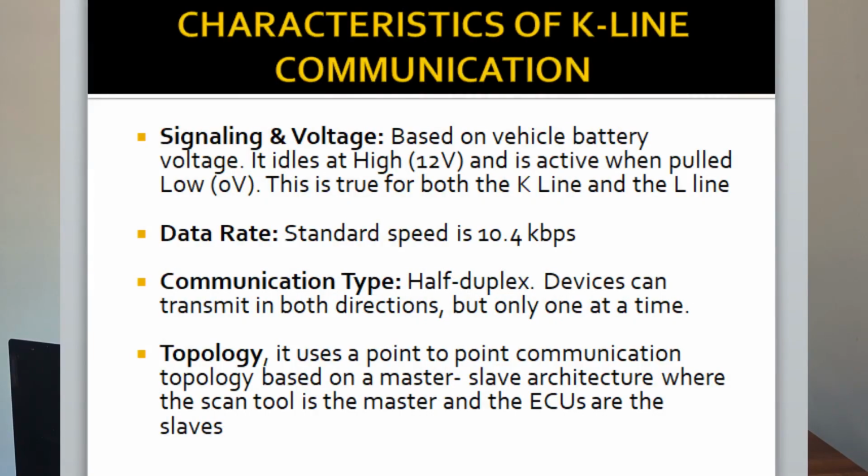Next, let's look at the topology. Now the K-line employs point-to-point topology, which is based on a master-slave architecture. Now what do I mean? When you plug your diagnostic tool into the OBD2 port, that tool acts as the master, and the control modules will act as slaves.